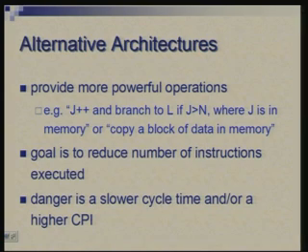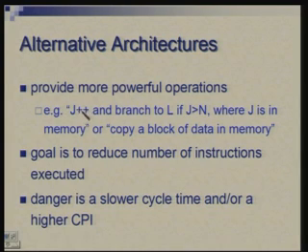So, firstly, in terms of operations, there are processors which define very complex operations as a single instruction. So, here are some examples. You could have an instruction which takes a variable in memory, increments it, compares it with some value, and branches to some target if the comparison succeeds. Okay. So, you have memory access, arithmetic which is incrementing, comparison and branching, all happening in a single instruction.